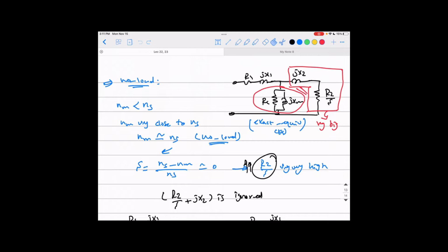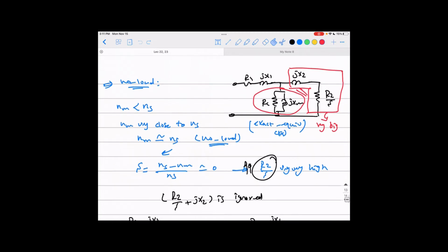In our last lectures we've been talking about the testing of the three-phase induction motor to determine the equivalent circuit parameters of this machine, so we can use it for any performance calculation related to the machine using the per-phase equivalent circuit seen here. We started with the DC test and locked rotor test, and from those tests we figured out how to find the resistances of the stator and rotor, R1 and R2, and the reactances of stator and rotor, X1 and X2, and then go into the no-load test to figure out the core representation, which is RC and XM.